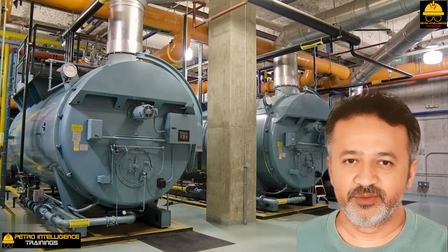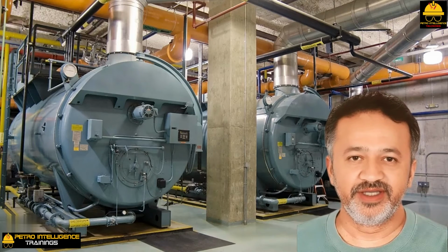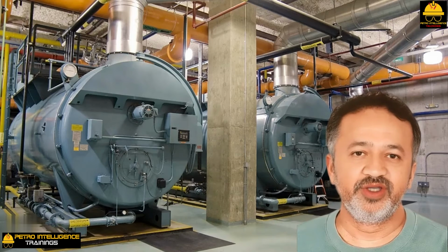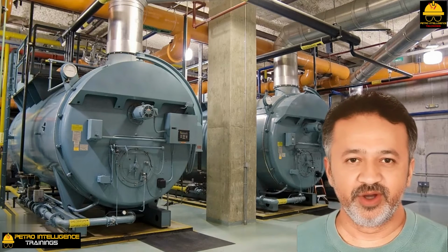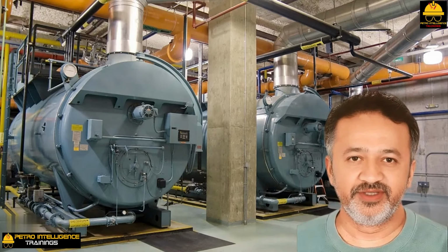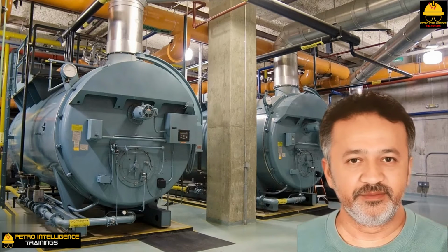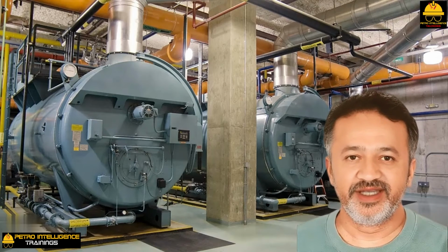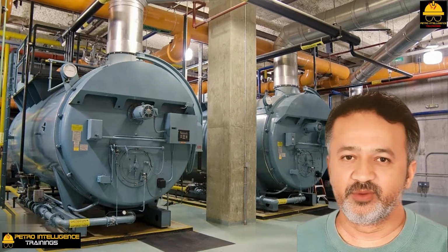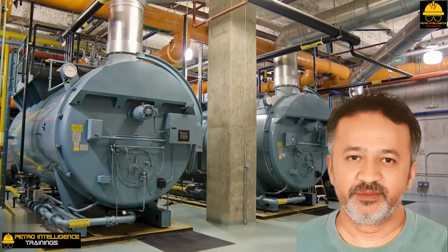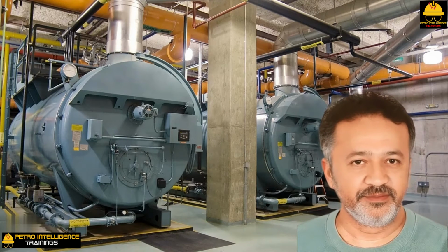The maximum allowable superheat coil outlet temperature is 700 degrees Fahrenheit to protect the carbon steel tubes from failure. At low steam generation rates, I have seen furnace firing rates, and thus heater charge rates, reduced to keep from overheating the steam above 700 degrees Fahrenheit. If the steam is not used eventually to drive turbines, or as a reactant in a catalytic process, such as a steam methane reformer for hydrogen or ammonia production, then the heater capacity is being limited for no logical reason.